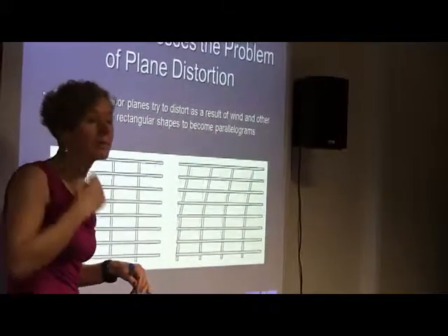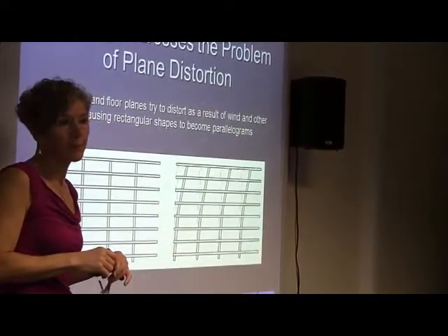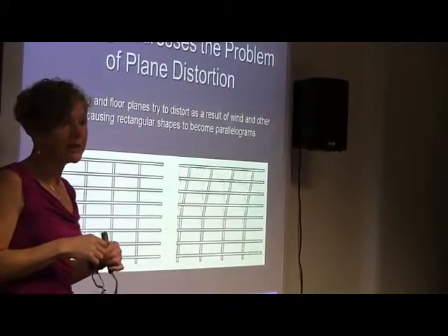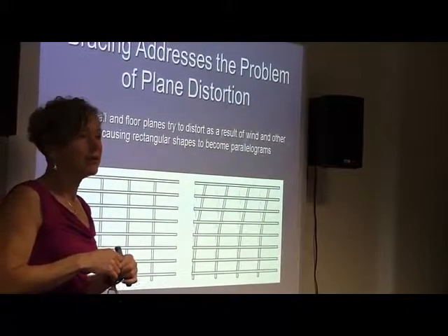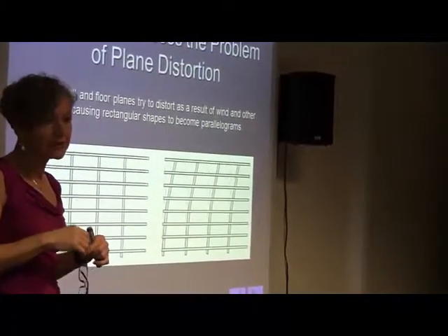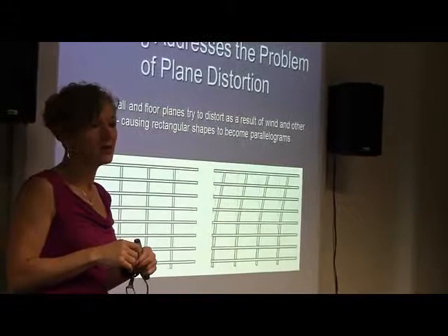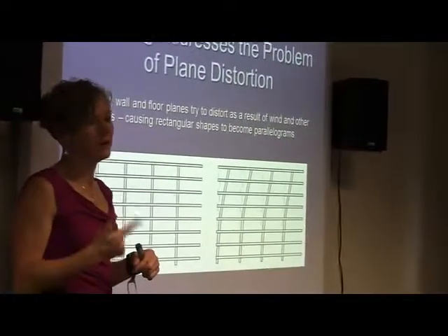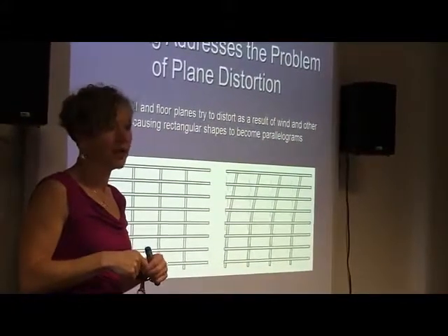For walls, is it 2 nails per stud? Generally, for your bracing, it's 2 nails per stud, but for all the different types of bracing, AS 1684 tells you exactly what size of nail or fixing and how many of them and where they need to go.